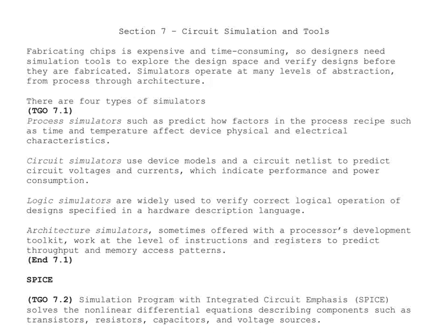Circuit simulators use device models and circuit netlists, so we're going to be learning about circuit netlists today, to predict circuit voltages and currents which indicate performance and power consumption. Logic simulators, you guys have done a lot of this already, are widely used to verify correct logical operation of designs in a hardware description language.